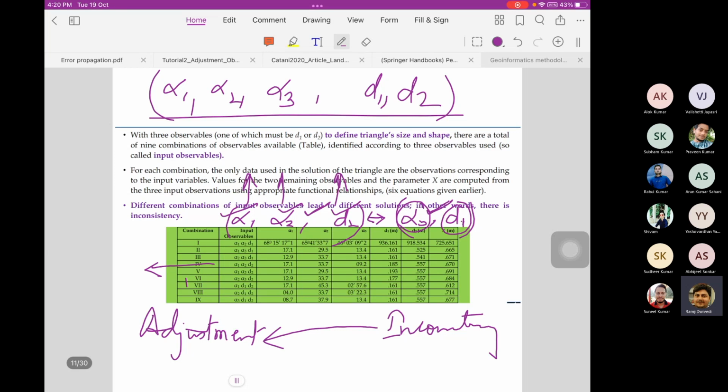Averaging is done when you ensure that everything is equal. Now, if inconsistency is there, there must be some reason due to random errors. Let's say just average it out. But now you know that a certain set of observations is very much precise, way beyond the quality of the other group. Why would you go for average? That is the blunder you are making.